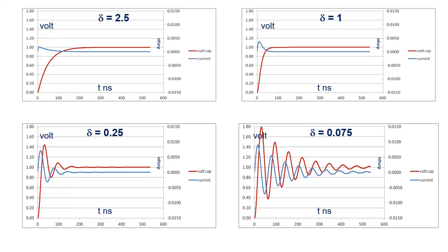This phenomenon might create a problem with digital circuits where we would like the pulses to be as clean as possible. This ringing may result from parasitic, that is undesired, inductance and capacitance present in the circuit inadvertently.